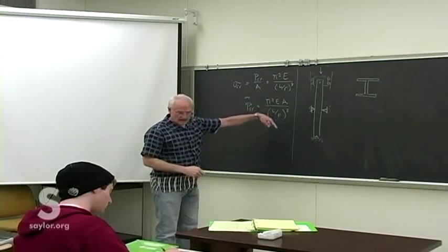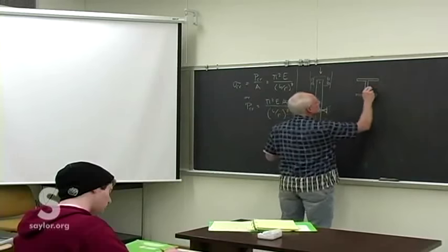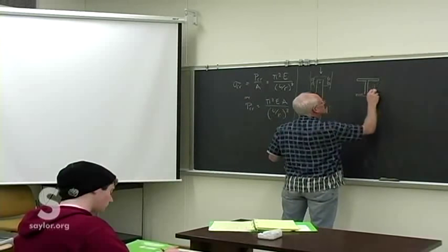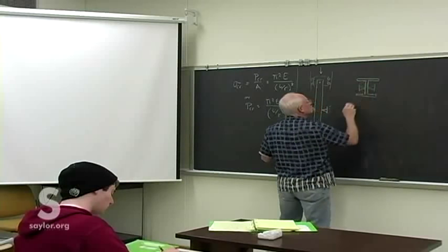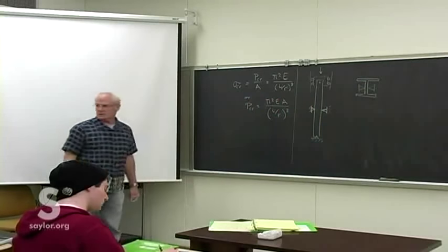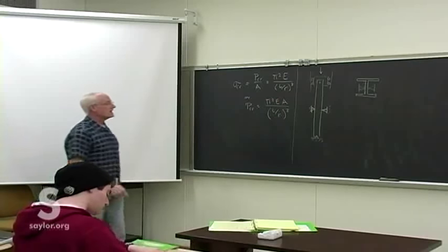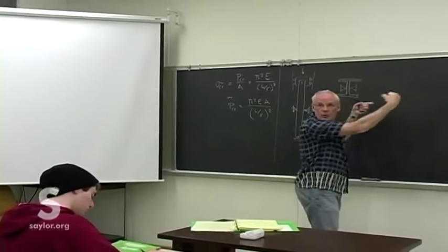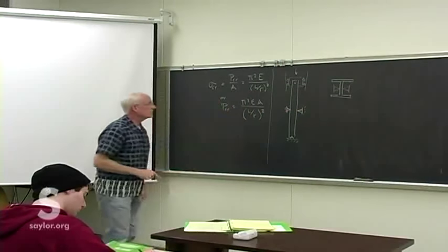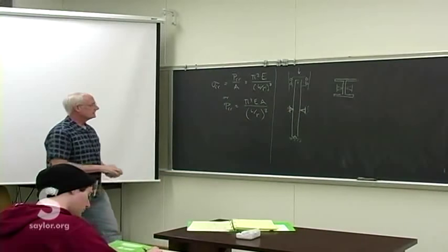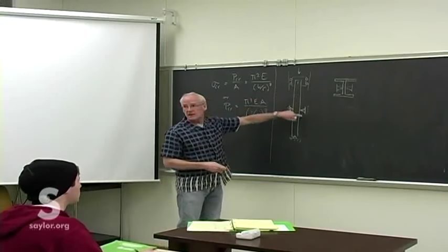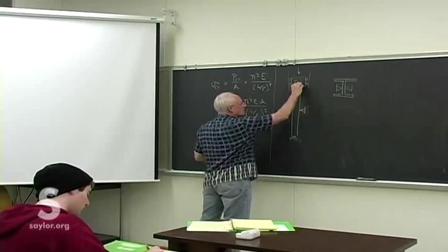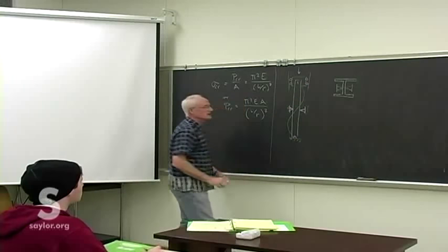We'd be looking straight down it, and we would see these supports, but they're all the way down at the midpoint. So it's oriented in that way, as opposed to it being an H-beam with two mid-supports. So it's supported that way, which means in the plane pictured, possible mode of failure is the second mode.